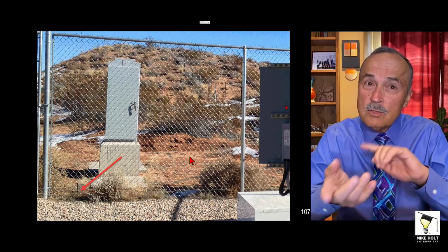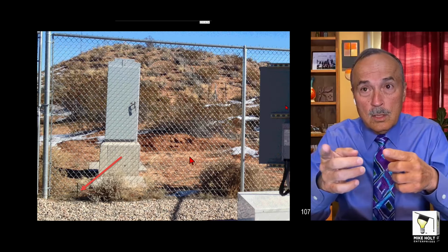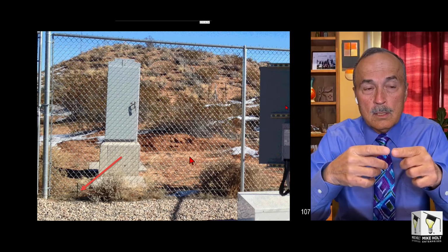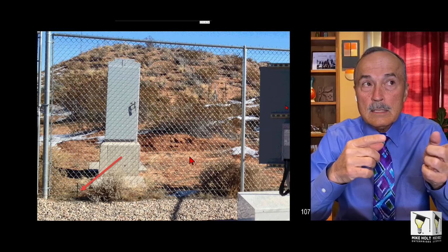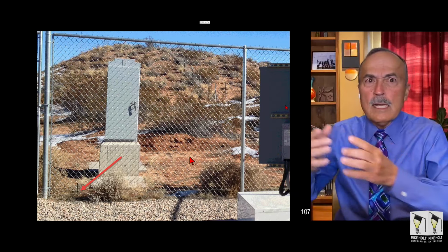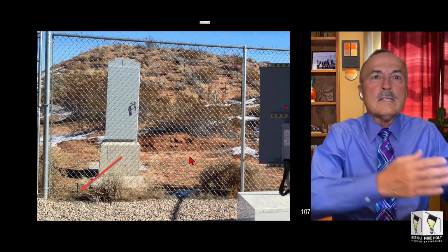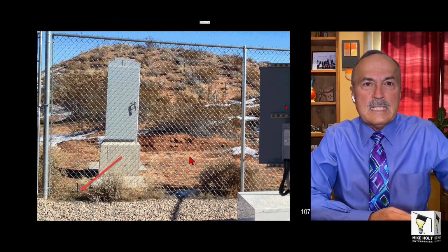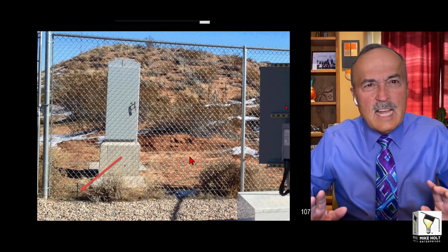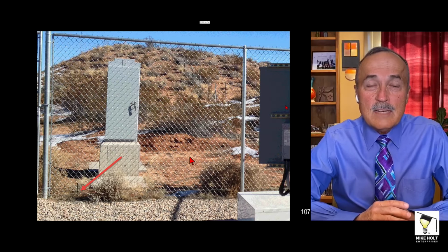To understand electricity backwards, see, we're working off AC with power going to loads, where solar guys are working backwards. They're actually generating power. Instead of being a load, they're going the other way. And it's not AC, it's DC. So you're getting power generated in DC, then you're converting it with an inverter over to AC. And the code rules in 690 and 691 and 705 and 706 and 710.